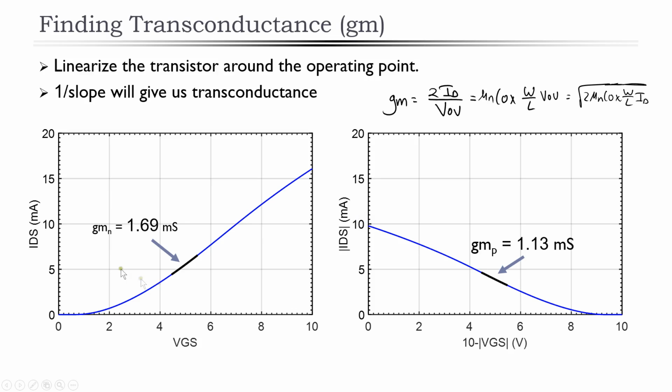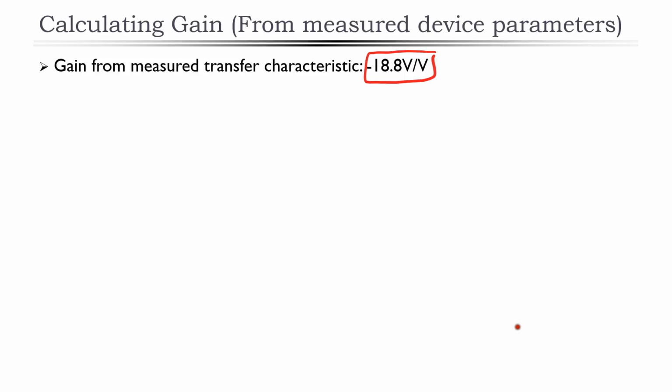But for now, let's focus on the fact that we have extracted once again, from the DC operating point and the IV characteristic, the small signal parameters required in the equation for the gain. And again, repeating ourselves, it was the same thing that we did for RO. Our transconductance is only valid within some range around the operating point. If we deviate too far from that, we can no longer approximate it with a straight line, and we can't just take the slope simply.